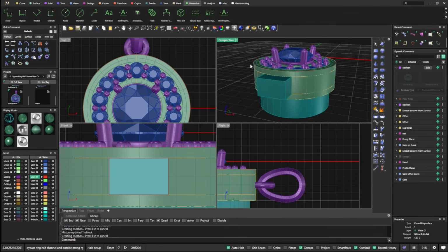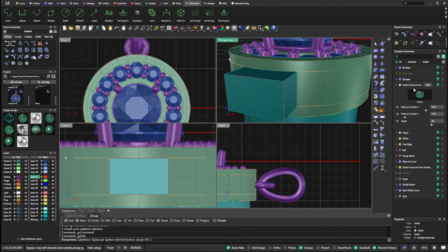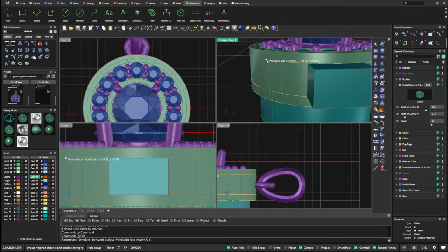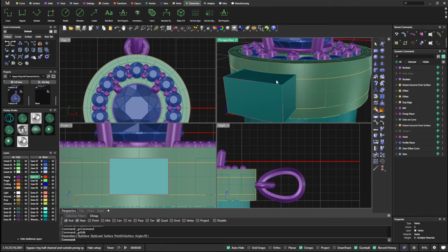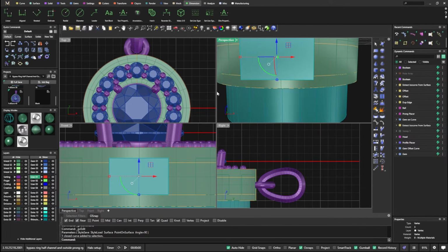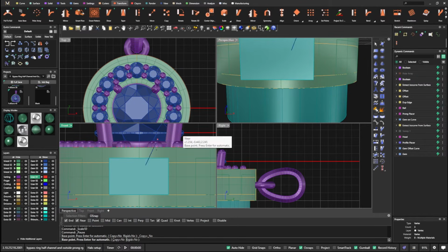There we go. All right, so we should be able to select this ISO curve. It didn't pop up over there. There it is. All right, edit, and now we can maybe make this just a little bit smaller, right? And we can edit that, and then we can take this curve here where our Boolean is, right? First what we'll need to do is, well, easiest way to do it would be just go to transform, go to our scale 1D, and go from here to here.